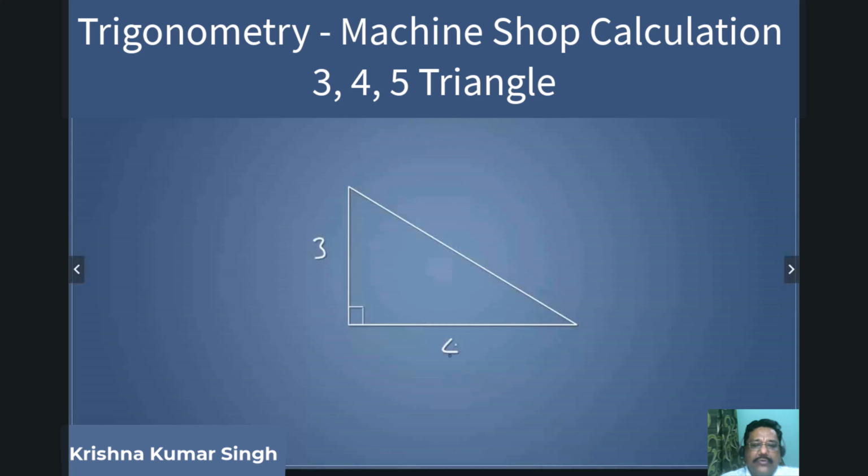So now, introduction of the 3-4-5 triangle. The 3-4-5 triangle is a right angle triangle with sides of lengths 3, 4 and 5. This is the smallest possible whole number set that forms a right angle triangle. It is widely used in various fields, particularly in the building industry, to create accurate right angle corners.